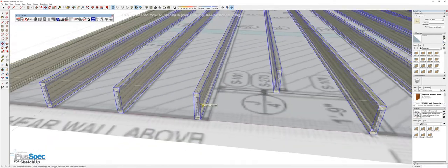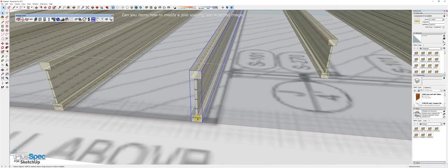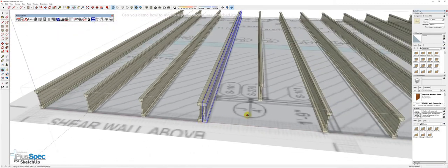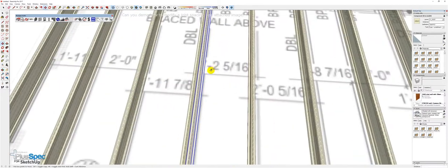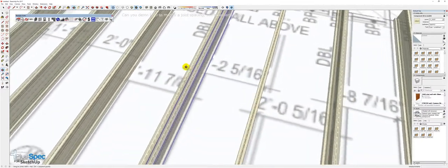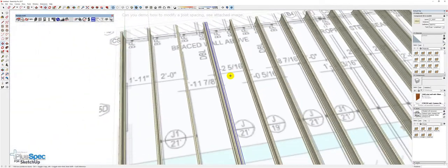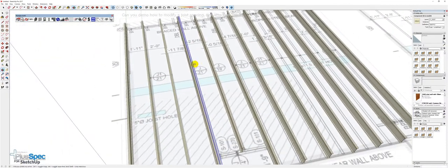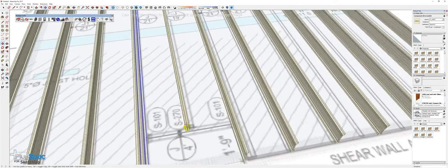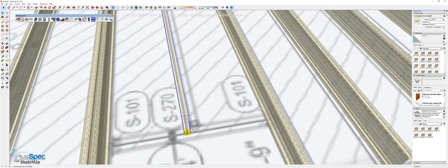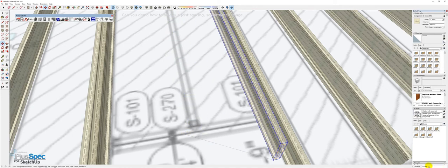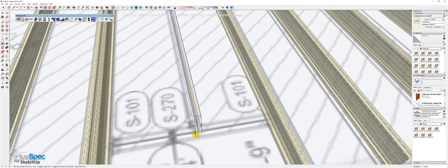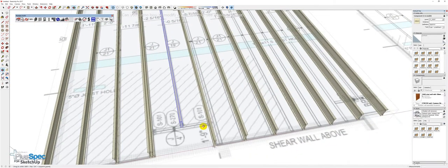However, we have a double joist here, so that means that basically what I want to do is I want to grab this joist, and I just want to move it over so I have a double there. And this one here, it does tell me what the distance is up here somewhere. It looks to be 1 foot 2, whatever that is, 5/16. Regardless, I can do exactly the same thing as I did with my tape measure line and move that over. Or I could just go off the drawing and trust that the scale is correct, and I can move that joist to suit what the spacing is drawn on there. You can type in the distance. If you notice in the bottom down here that we can type in any distance we want to. Okay. You can see that I need a double joist here.